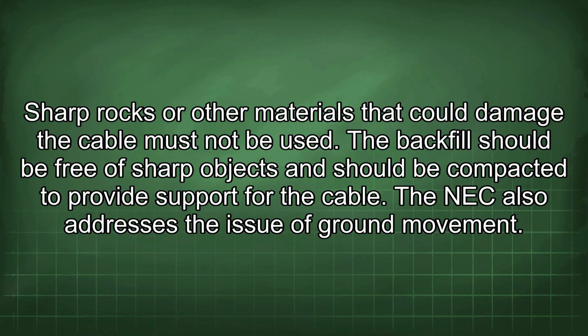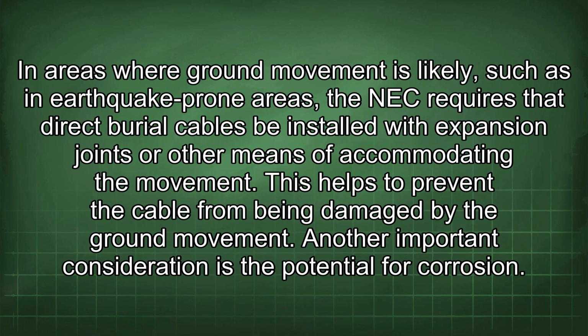The NEC also addresses the issue of ground movement. In areas where ground movement is likely, such as in earthquake-prone areas, the NEC requires that direct burial cables be installed with expansion joints or other means of accommodating the movement. This helps to prevent the cable from being damaged by the ground movement.